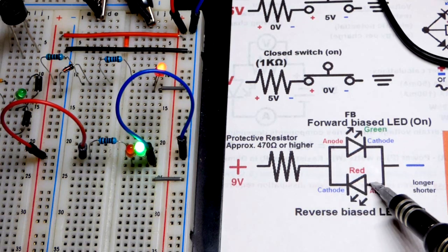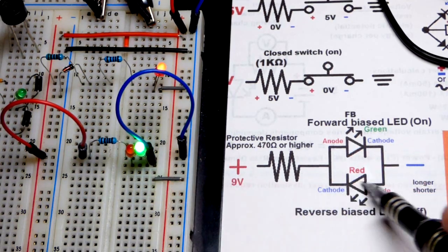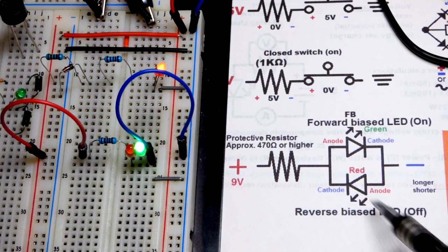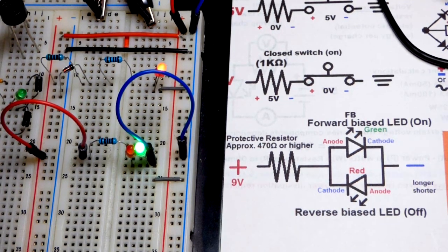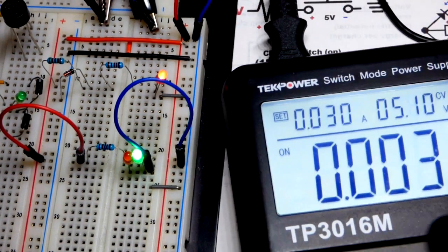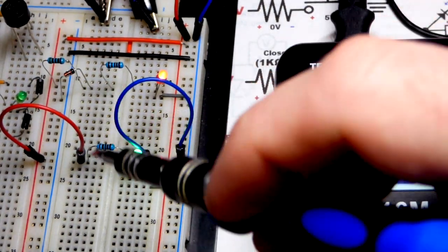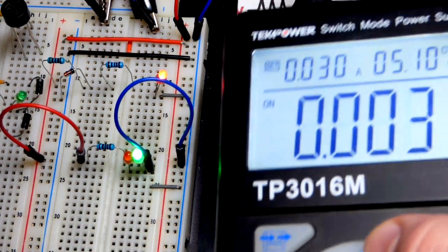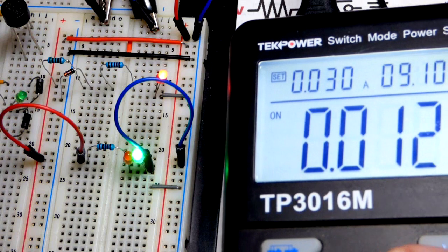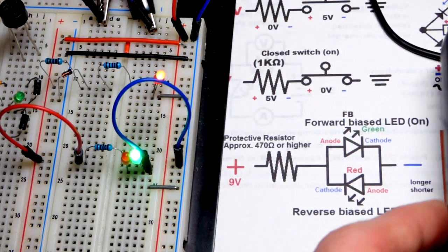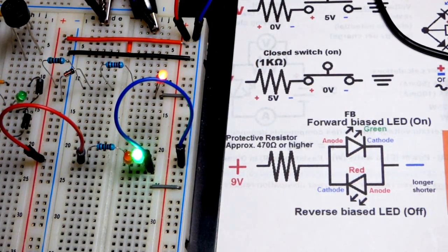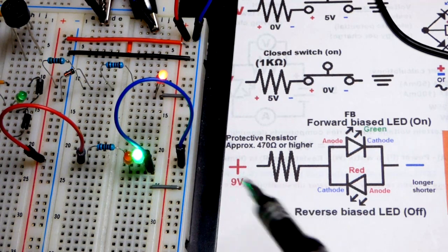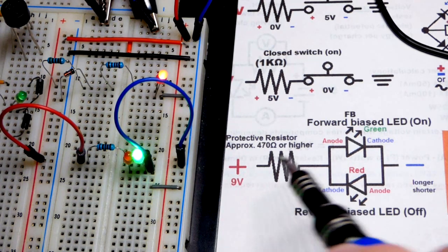So that one's going to block it. And so we only got about 3 volts built up across that LED. We actually have 5 volts at the supply right now. I'll raise it up to 9 volts really quick. We can do that. It's a 1 kilo ohm resistor, so we got plenty of resistance. And so there we go. We got 9 volts, and it's still protecting it. So I just did that because I wrote 9 volts on there. Again, you can modify as needed.